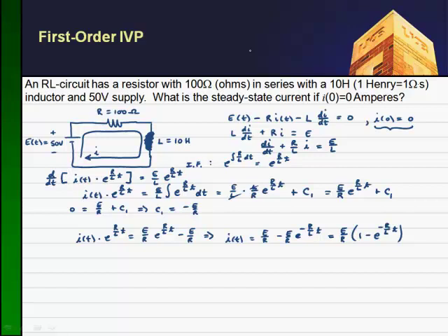And if we recall Ohm's law, if the potential source is constant and the resistance is constant, I really get a constant current here. So this could be written as I of t is equal to, in some textbooks you may see I naught or I max, I'm just going to write it as I, times 1 minus E to the minus R over L t.